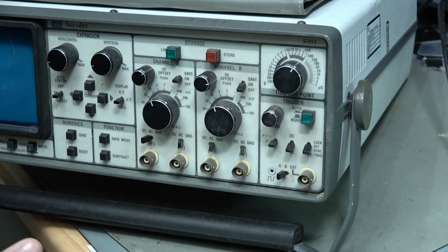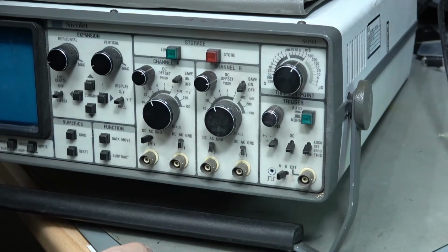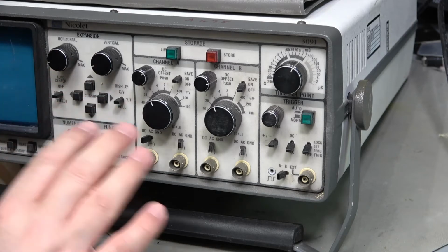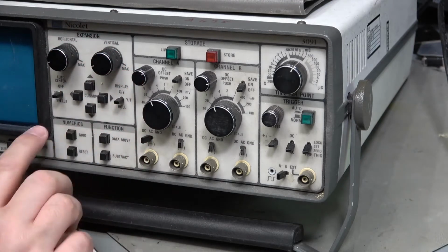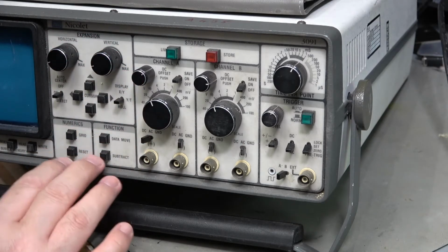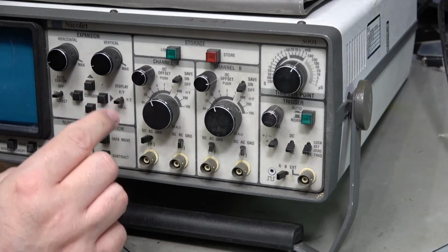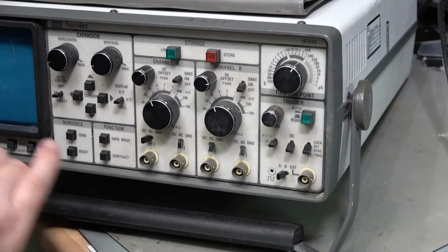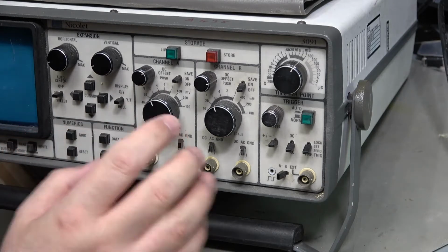What else is different about this? Obviously, this storage, and it can take some bubble storage in the back, but it hasn't got the bubble storage unit in it. The bubble storage only stores 5 traces, so it's not really worth writing home about. Obviously, we've got various playback controls over here. We've got numerics, grids, data movements, subtractions, cursor movements, whether you want XY display or Y time or a rolling display. So it's quite interesting from that point of view.